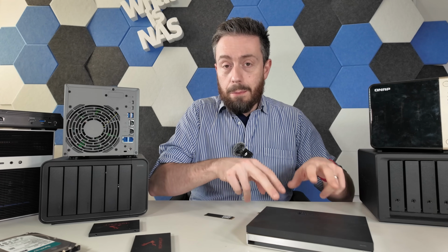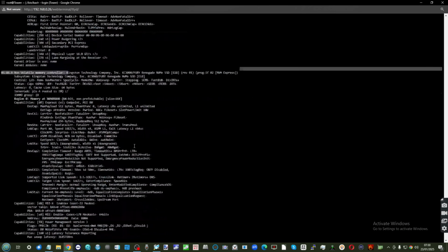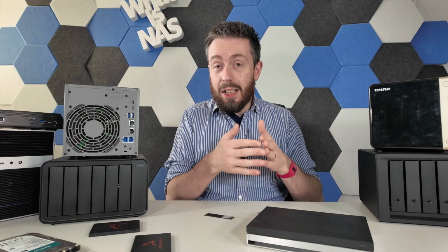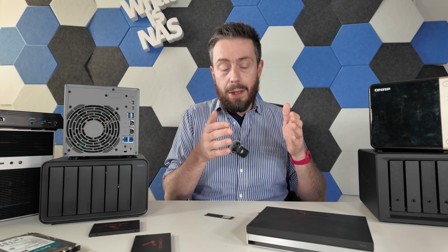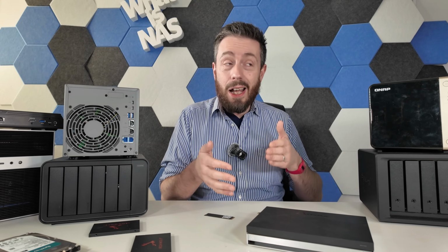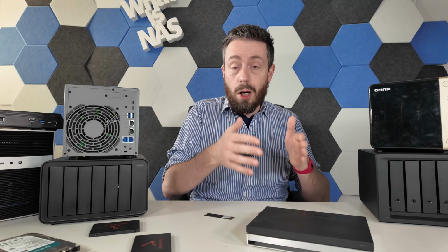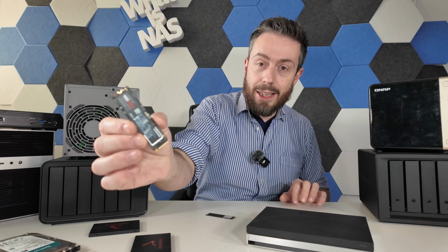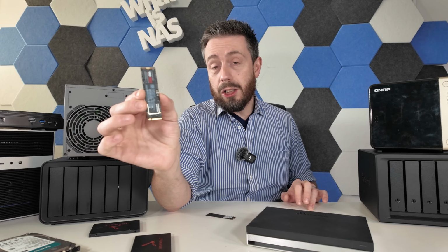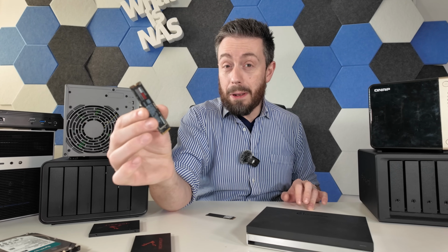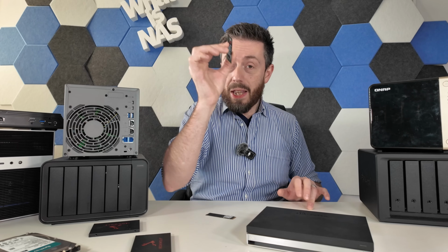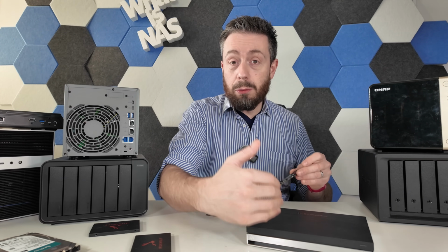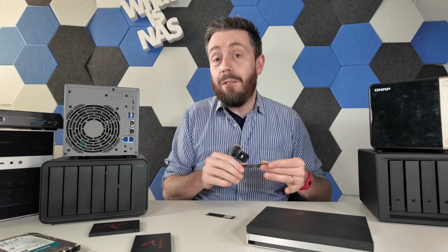Number one, this system here, the M.2s inside, are at Gen 3 x1. Now, Gen 3 x1, although it is listed as a gigabit, really in terms of performance, or a gigabyte I should say, that does still mean you're only going to get around about 800 to 900 megs on a 3 x1 lane, realistically, and that's megabytes. Now that means that even though an SSD like this one, the Samsung 980 Pro, which is a Gen 4 x4 drive, promoting speeds of 7 gigabytes per second in read, it is not going to be able to outstep that 800 megs on each individual M.2 there, and even the PCIe switch they are fed into there.